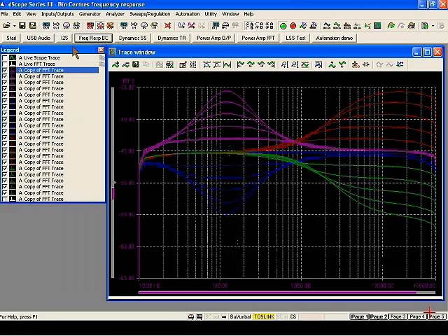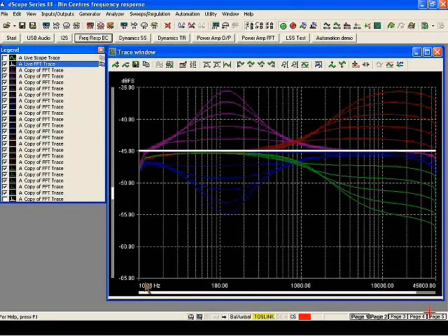What I'm going to do now is turn on my live FFT trace, and this FFT measurement is actually plotted with exactly the same number of data points as the stimulus, so in this case 8,000 points. That gives me 4,000 points of data in this frequency response measurement, and although you can't really see it terribly clearly, it's updating at a very fast rate. This red bar at the bottom here shows you the progress rate, and we're getting several, 3 or 4 frequency response measurements every second.